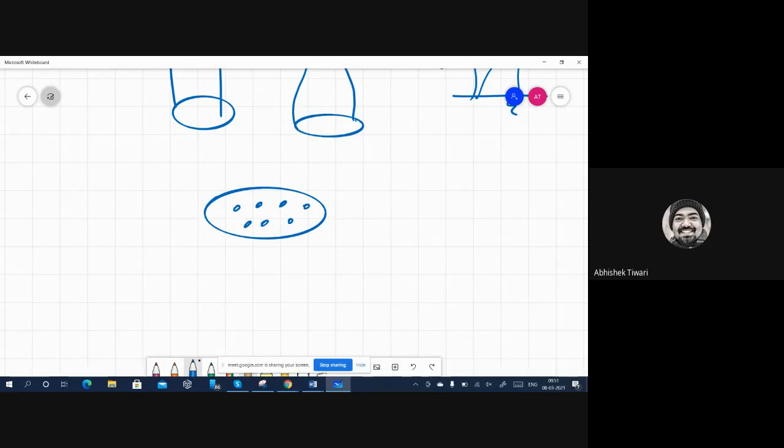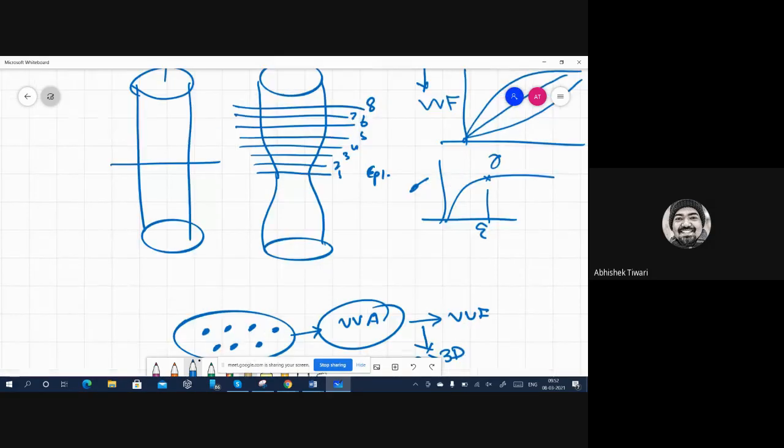And these voids will either look bright or dark, depending upon the field you're looking at. So there will be a contrast. So the rest of the thing is continuum, and these are voids, and then you calculate the void volume area, and assume that it is also the void volume fraction. Here is the error because of 2D to 3D conversion, and you cannot avoid it, but this is one of the ways how you put damage kinetics into the picture. Okay, there are other ways also.